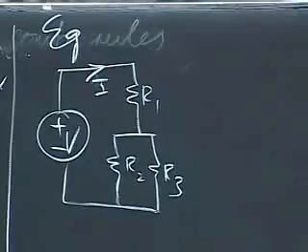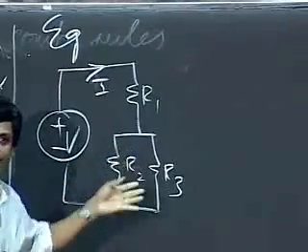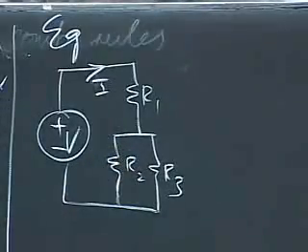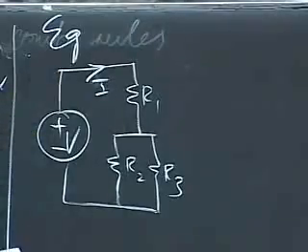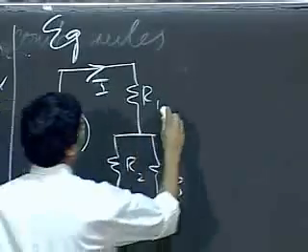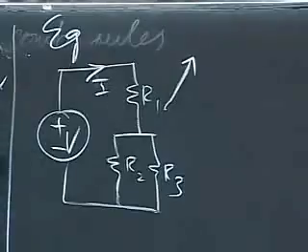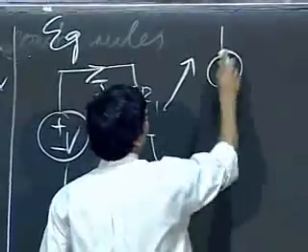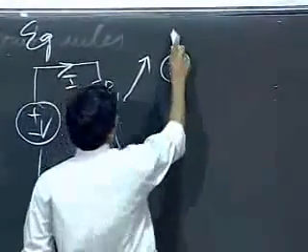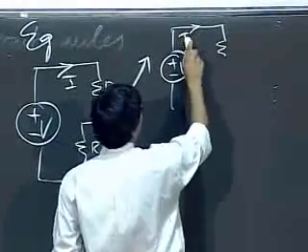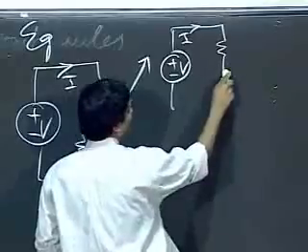Of course, you can go ahead and write KVL and KCL. You will get 4 equations, and there are 4 unknowns, and you can solve it. But I can apply my element combination rules and very quickly figure out what the current I is using the following technique. So what I can do is I can first of all take this circuit, and I can compose these 2 resistances and show that this circuit is equivalent, as far as this current I is concerned, to the following circuit,